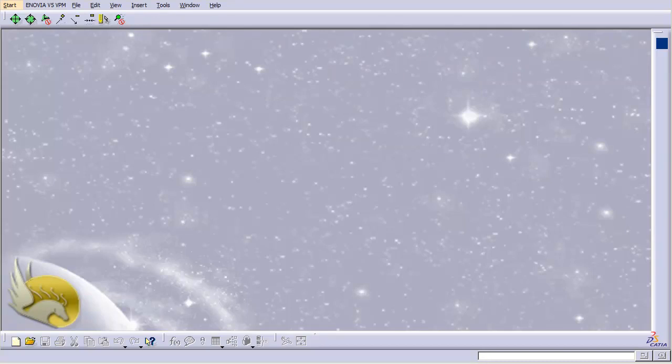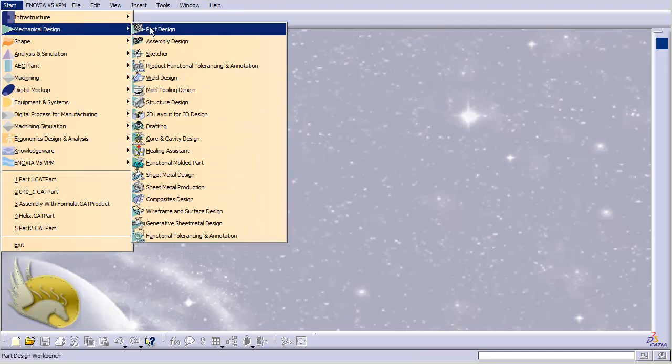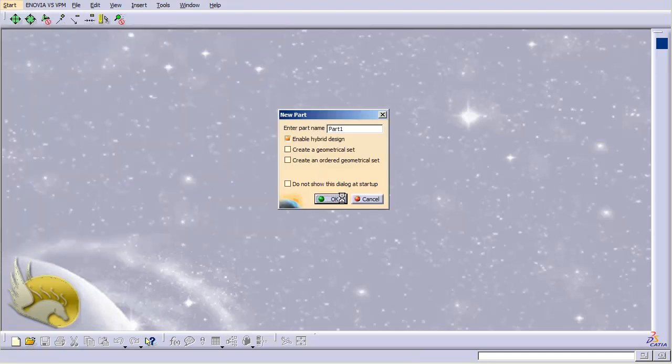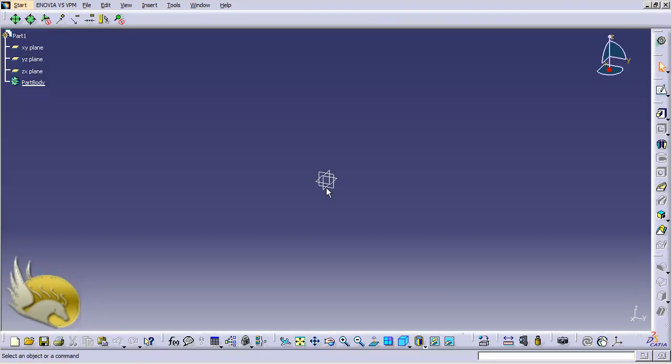In this section, I want to give you another example of assembly that's going to be a little more complex this time because I'm going to create complex parts here. And next, I want to assemble them and show you how you can have an explode view of your assembly. Now, this is going to be another practice, so I go to mechanical design, part design, and I start part 1 here. The first thing I want to create is to go to YZ plane.